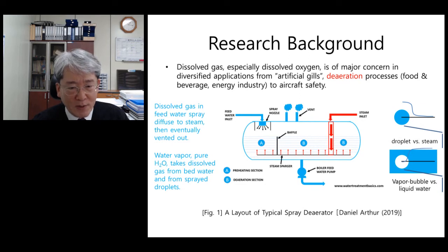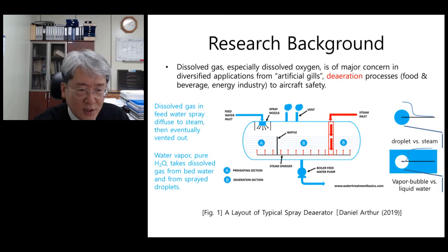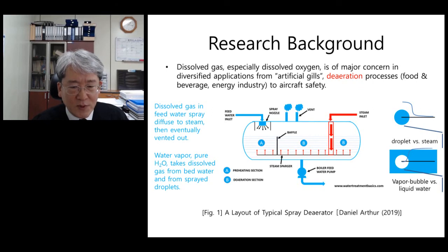The principle of the aeration is based on the diffusion between the gas dissolved droplets and pure steam, and between steam bubbles and the gas containing liquid.